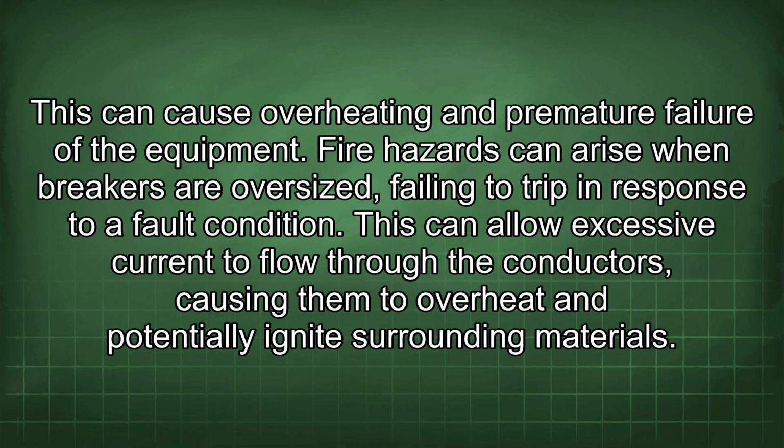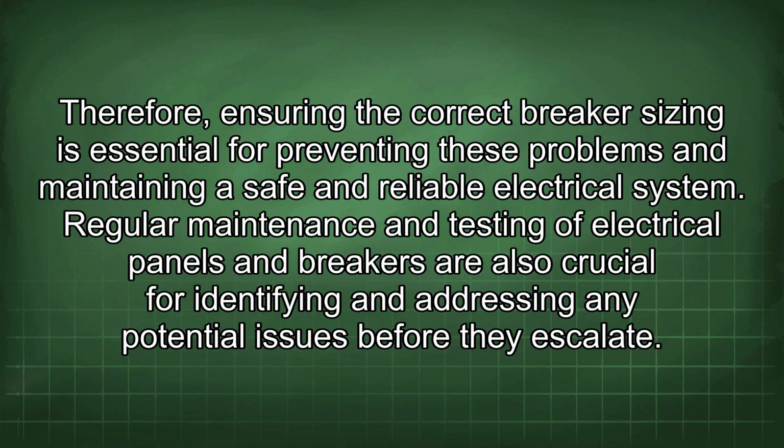Fire hazards can arise when breakers are oversized, failing to trip in response to a fault condition. This can allow excessive current to flow through the conductors, causing them to overheat and potentially ignite surrounding materials. Therefore, ensuring the correct breaker sizing is essential for preventing these problems and maintaining a safe and reliable electrical system.